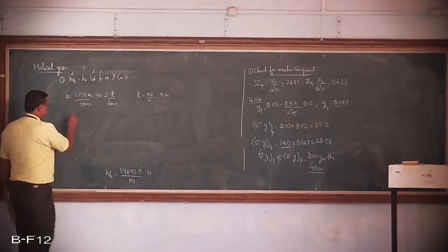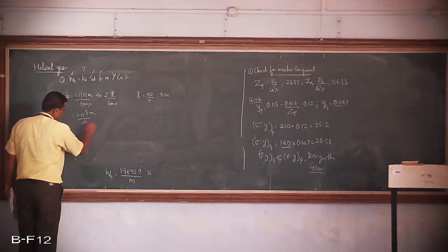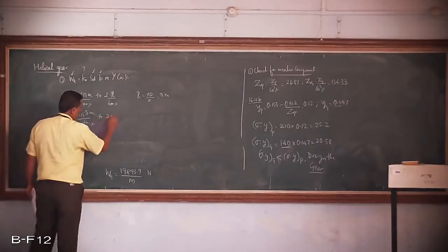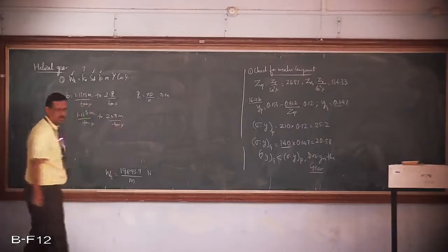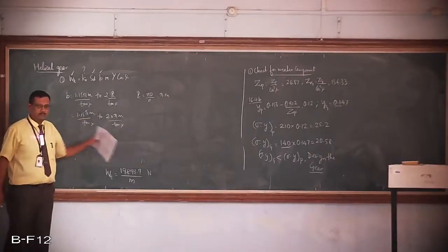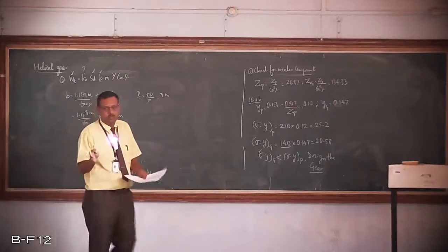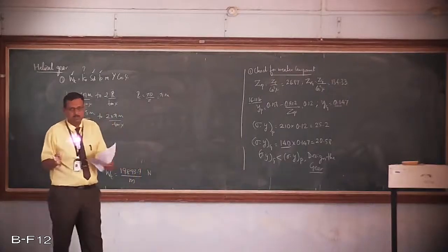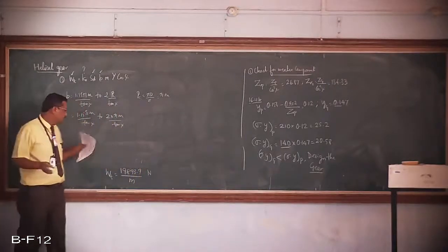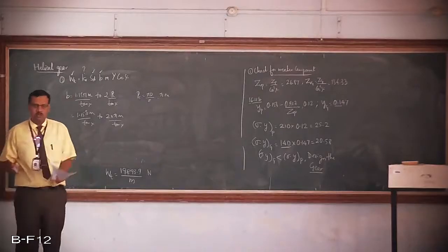Therefore, the equation gets modified to 1.15 pi m divided by tan of phi to 2 into pi m divided by tan of phi. Therefore, you get a range, 7 point something to 12 point something. You are free to assume the value of width between any value in that range. It is not a hard and fast rule to assume only one value.